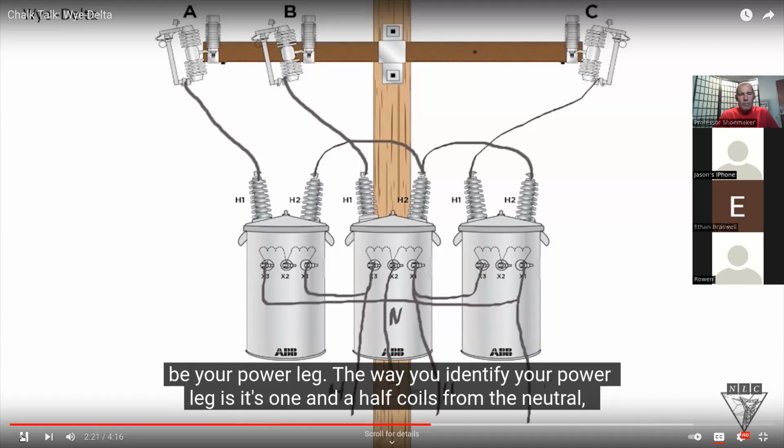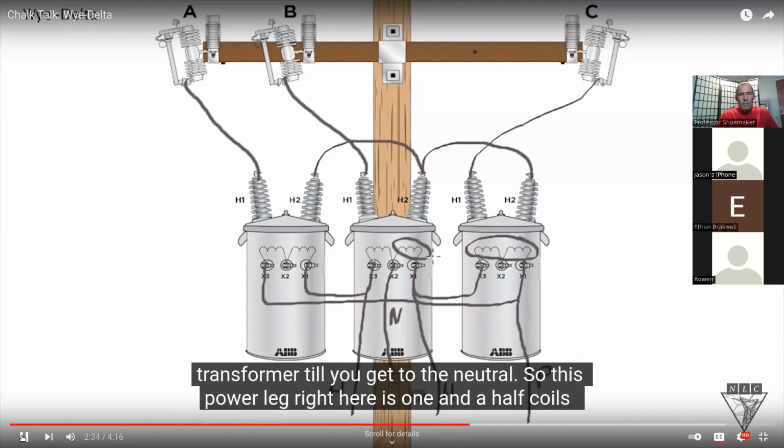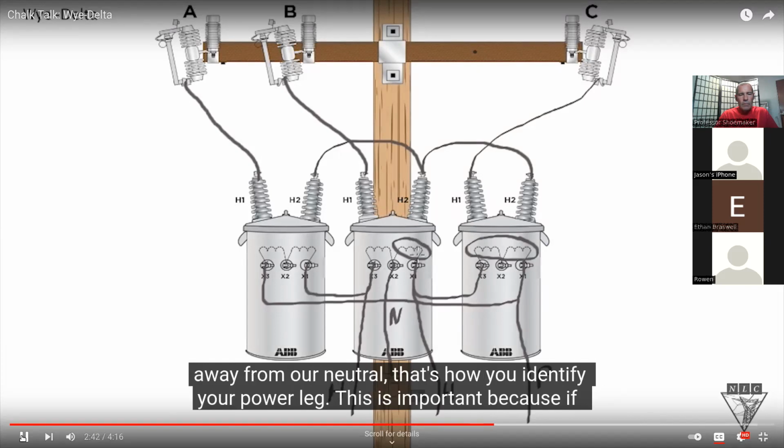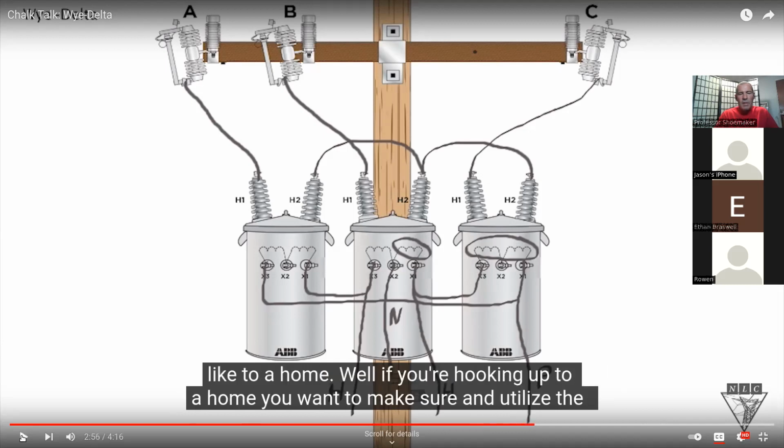Your last connection is going to be your power leg. The way you identify your power leg is it's 1.5 coils from the neutral. What I mean by that is we've got one full coil in this transformer, half a coil in this transformer till you get to the neutral. So this power leg right here is 1.5 coils away from our neutral. That's how you identify your power leg. Now this is important because sometimes you can be using these connections and you need to hook up a single phase load, like to a home. Well, okay, that's the same thing he's discussed before as far as open delta was concerned.